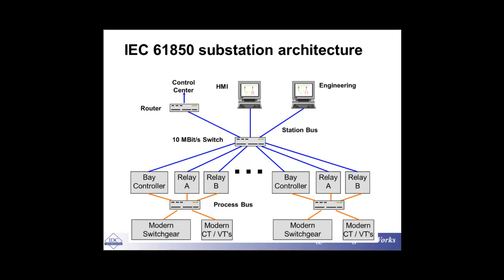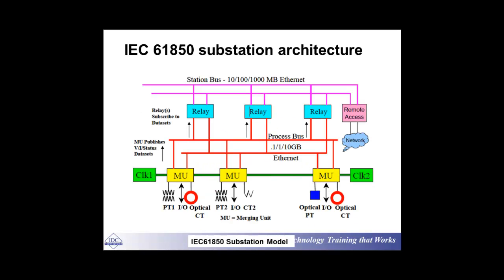So we have to look at it like that, and if we look at it like this, everything should be programmable, should be able to be modeled, and should be able to be put in a mainframe, so that you can say that this belongs to the process bus, or this belongs to the station bus, or that can be the input to the station bus, and that can be the output to the station bus. So this is the way you would define an automation system in the IEC 61850. That is the main aim.